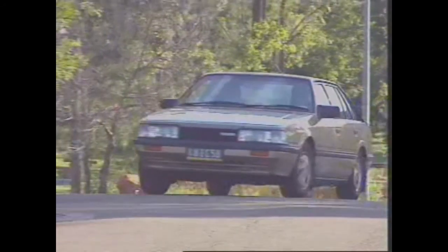Closing some orifices makes it harder for fluid to flow through the piston. This increases the dampening effect of the shock absorber, providing a firmer ride, more suitable for higher speeds and faster cornering.